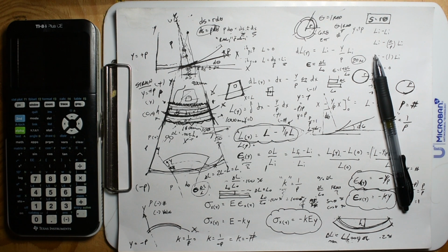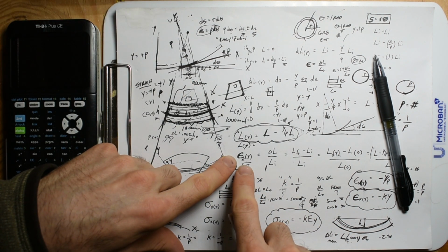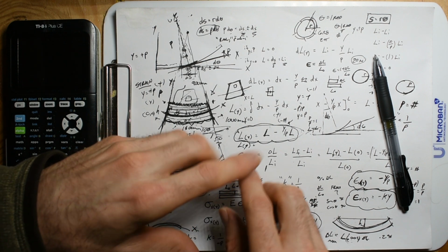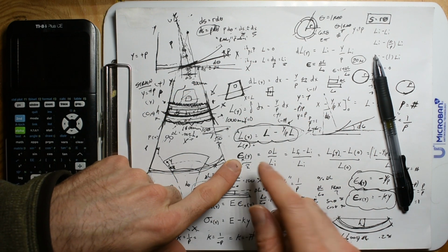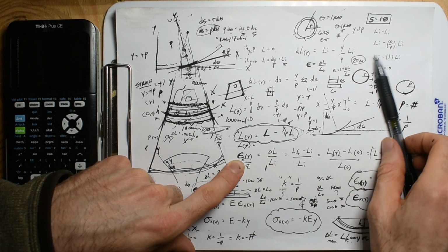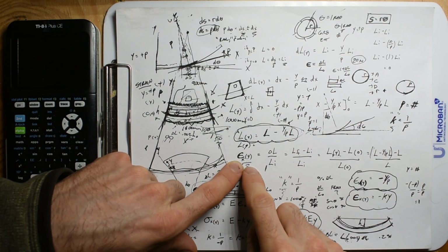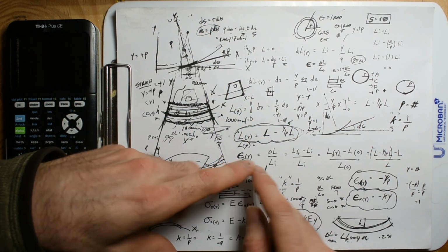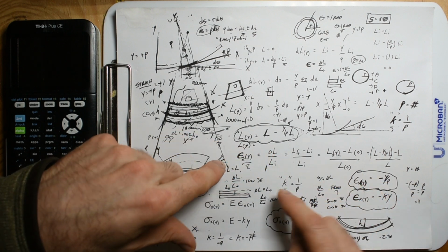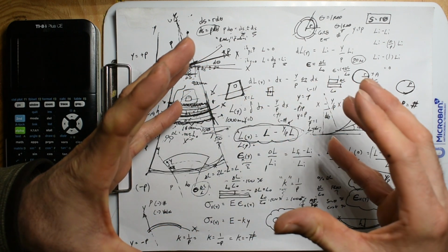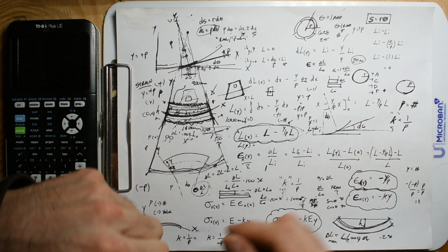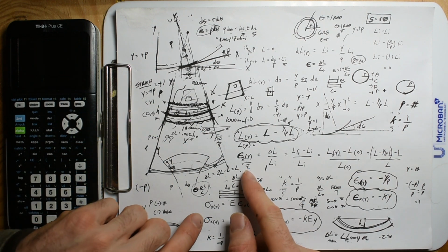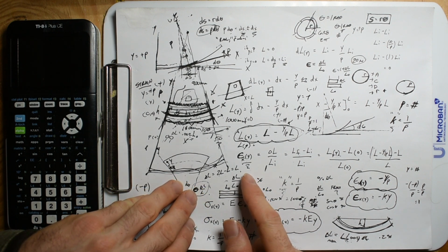But I think that is one of the harder take-homes of what strain is giving you. It's another way to say pounds of force, even though strain is wrapped up in this bizarre little fraction. It's a percent of the change in length. It's not the new length itself. This number doesn't give you that 1,000 to 2 millimeters. It gives you the percent change in length.